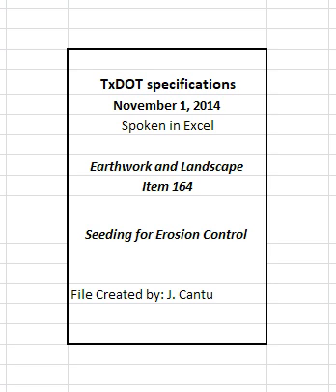Clay soils with slopes of 3:1 or less, 2,000 pounds per acre. Clay soils with slopes greater than 3:1, 2,300 pounds per acre. Cellulose fiber mulch rates are based on dry weight of mulch per acre. Mix cellulose fiber mulch and water to make a slurry and apply uniformly over the seeded area using suitable equipment.